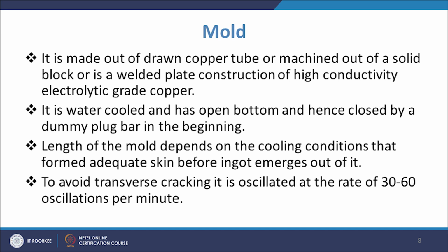Initially we close it with a dummy plug bar, and then water will be coming and flowing, absorbing the heat which is released by the liquid metal in the mold. That is why you will have a change in the temperature between the incoming water and the outgoing water, because the water takes the heat being released by the mold.